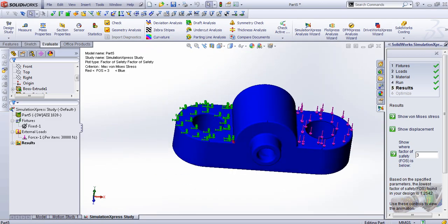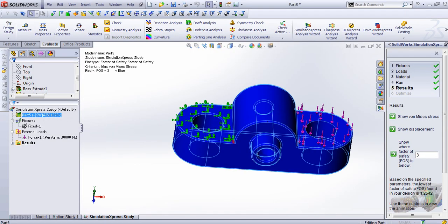There are 3 different approaches to solve this problem. Either I have to modify the geometry. I can show you, I could add a fillet here, and that would perhaps significantly help the situation. I can reduce the load, but sometimes these first two are not possible. And if that is the case, then the third option would be changing the material property, changing the material itself.